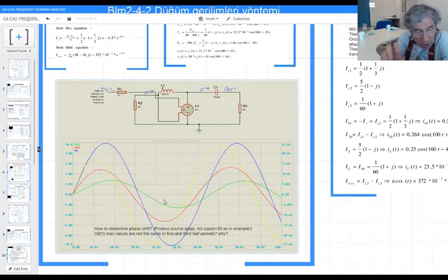So at the beginning there could be some changes, because of the transient solution, so the beginning part could be a bit different. But if you take your time scale here, which is 100 milliseconds, and make it 10 seconds, this part is not going to be the same in detail, and you are going to see exactly the particular solution, not the transient solution.